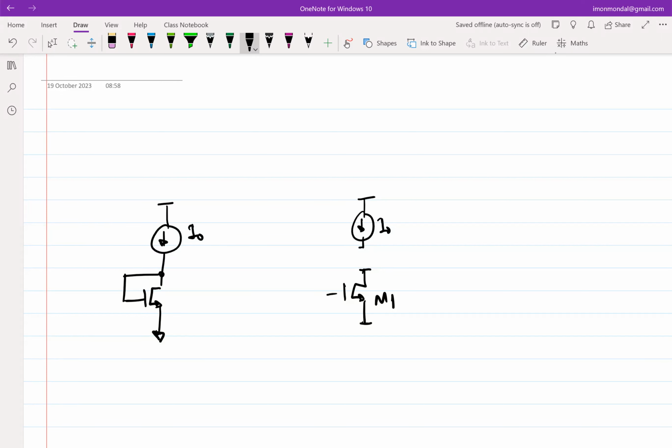And then we noticed that if we simply connect the current source to the drain of the transistor, this will not suffice, because the current through a transistor is not the cause, it's the effect of something else, right? It's the effect of the gate to source voltage that is applied between the gate and the source terminals of the transistor, which meant that we needed a framework to generate that gate to source voltage automatically, right?